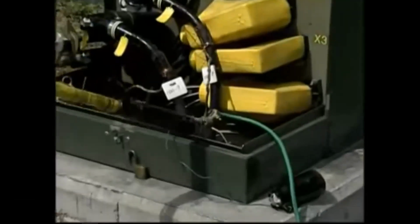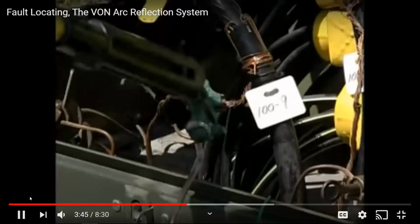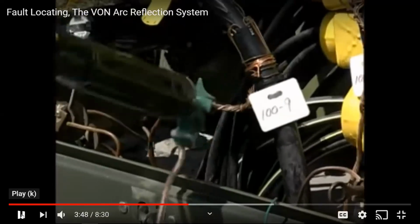Begin by attaching the green safety case ground. Then, connect the high voltage return to the concentric neutral on the cable being tested as close as possible to the cable termination. Okay, so there's a couple features going on here. That's a safety ground he put on, but you also need a neutral return path to the machine also. So really there's two grounds on this machine.